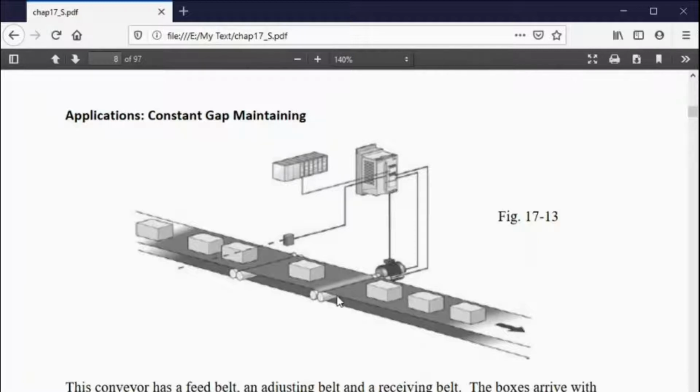So this conveyor can go faster or slower. You really have to ask yourself, first of all, is there slippage between this conveyor and this conveyor? In other words, can you put this box, jam it onto that conveyor? And the answer is probably yes. So that's one question. The other question is, are you able to have a little bit of variability between where the boxes are? In other words, do they have to be exactly X number of inches apart? If that's the case, then probably you do have to have synchronization between your drives, this drive and this drive.